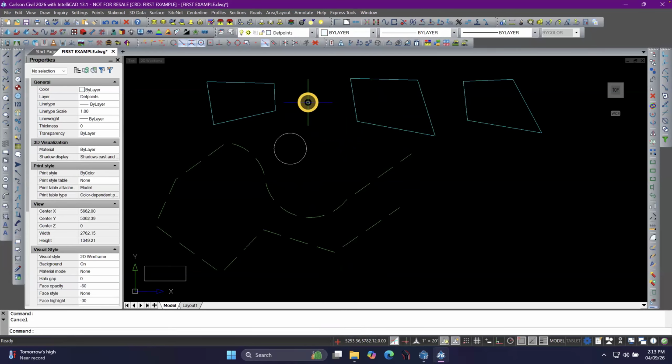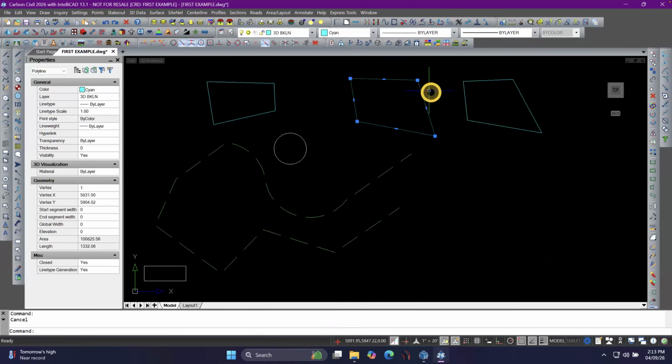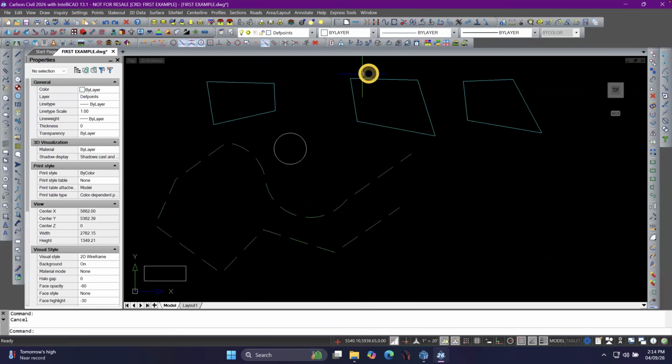So what I'm getting at is a lot of things that we draw, roadway alignments, a sewer layout, a boundary of a parcel of land, things like that, that's usually one figure. We want that one figure, a contour line that goes all the way across the map site. We want it from start to finish as one single entity. So a lot of things we want to turn into polylines.